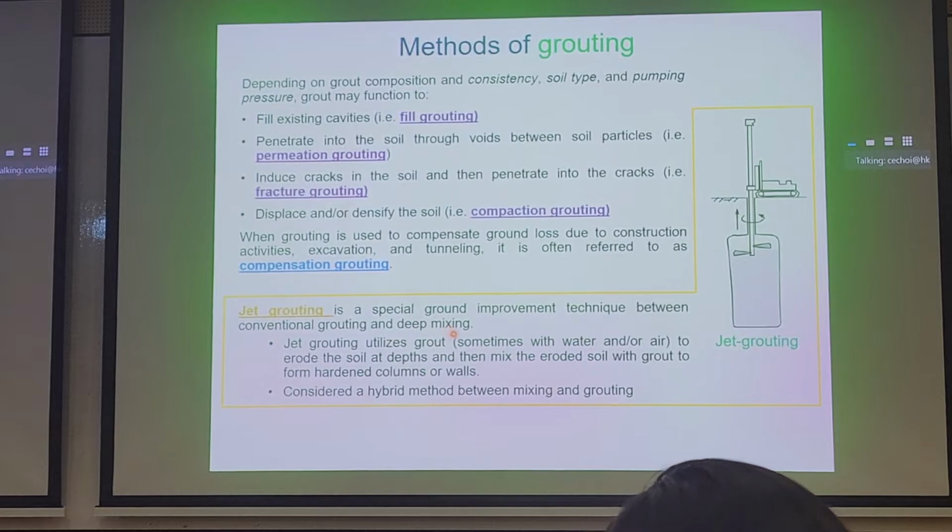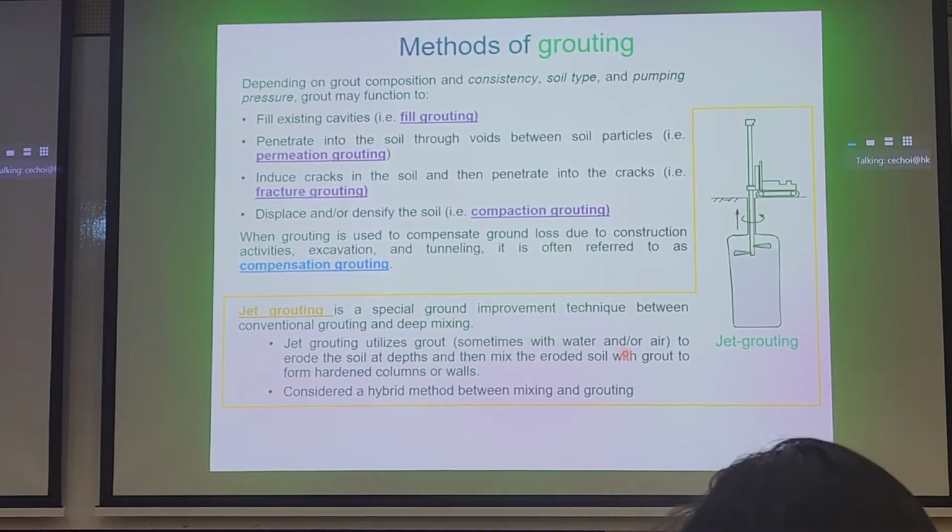And the triple, single, dual jet is basically just depending on what type of additional fluid you inject on top of grout, whether it be high pressure air or high pressure water. The air and water help to erode the in situ soil, so you can replace it with more grout material. High pressure air and water can also be used to flush out some material and lift it as well. So this is providing you with a bit more details of the different injection methods.